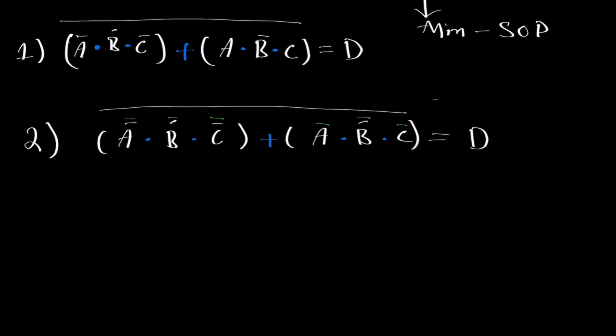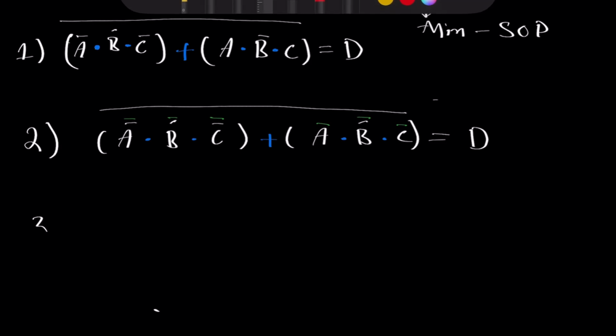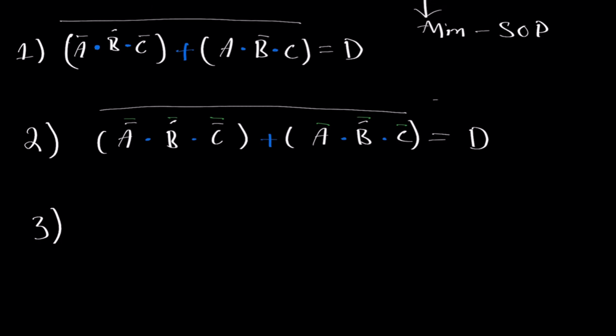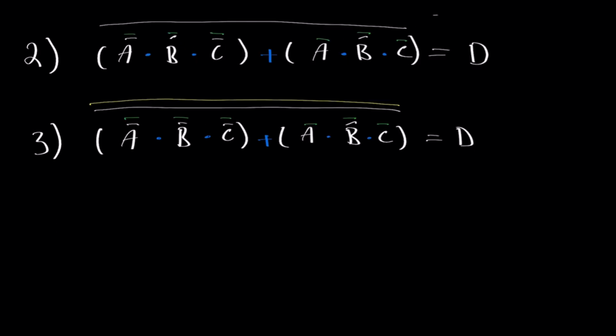And now moving up to step 3. Step 3 was complementing the whole function, or adding one long overbar to the entire function. Use a yellowish color. So in step 3 we will add a long overbar to the entire function, and that yellow over bar on the entire function is from step 3 because we are complementing the whole function. That will bring us to step 4.